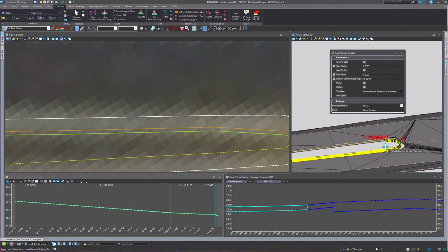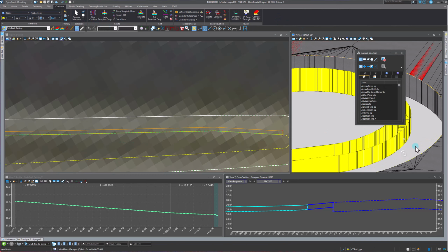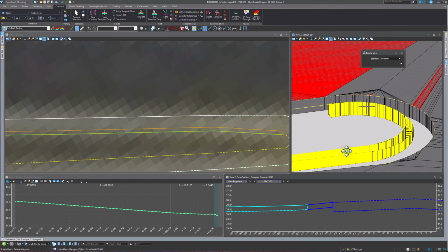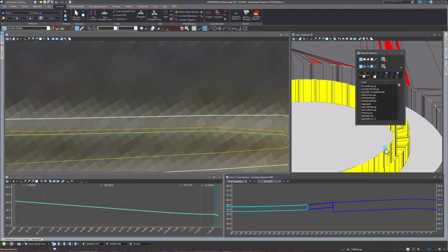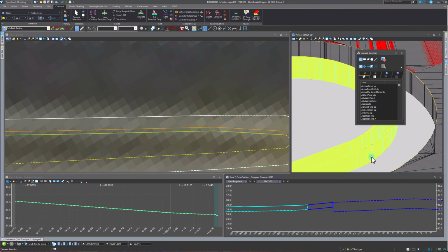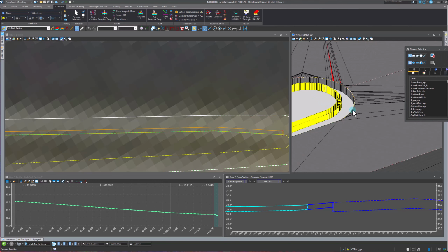so we've got our template, and see how it's very skinny right now. So what it's doing is here's our line right here for our curb back out, and then it's going down 1 foot, it's going over 0.5, and then it's shooting up and finding the existing ground. But we want it to find the existing ground at this edge of pavement.